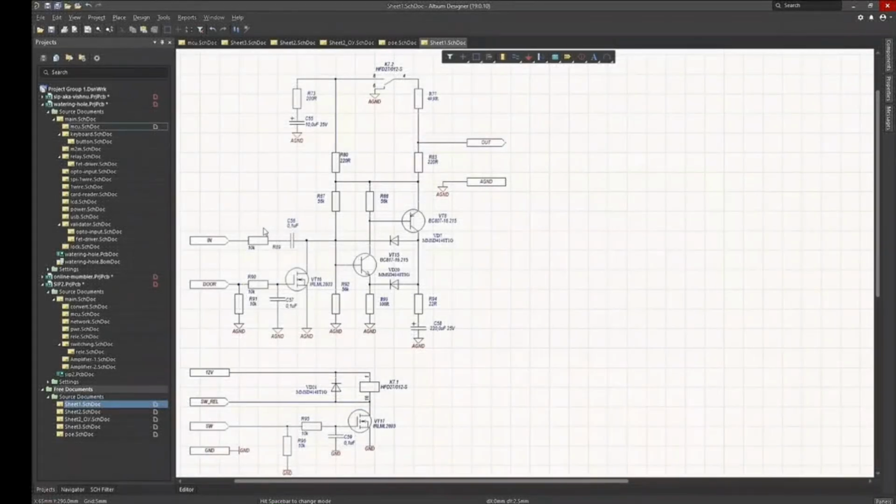Mistake number 7. Trusting schematics without verification. There are plenty of incorrect schematics on the internet that visually look correct. If you simply copy them into your project without checking on a breadboard, or at least in an electrical circuit simulator, then with a high probability you can get a non-working board or instability during startup and debugging. You will save time on circuit design and spend 10 times more time debugging the board after launch.